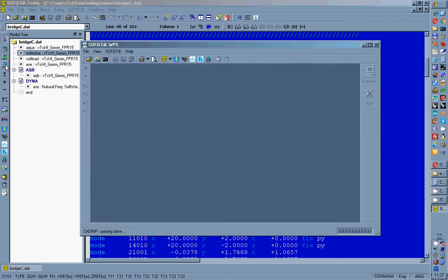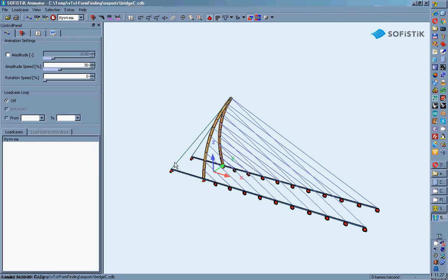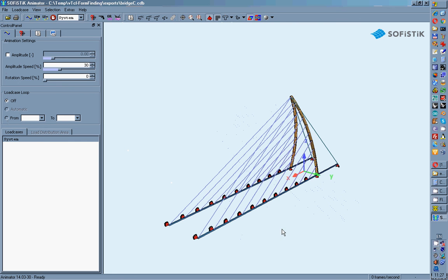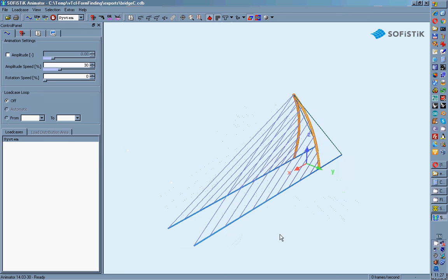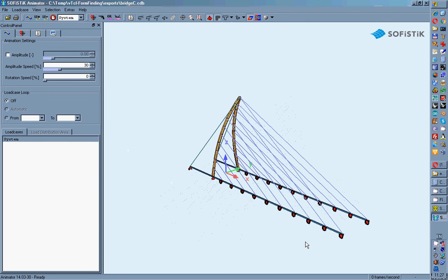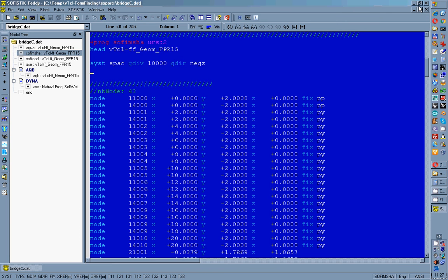And this is the geometry. For the geometry it worked, but we shouldn't have cross section. Well, we have the geometry. It seems that the issue is not a serious one. So we have the bridge in Sofistik, just to check that error in Aqua module. But we have the cross section, we have the geometry, symmetric geometry with the fixation. We have to remove all this fixation and replace them with beam, but it's a minor work we have to do. And we have a geometry that is in perfect equilibrium.